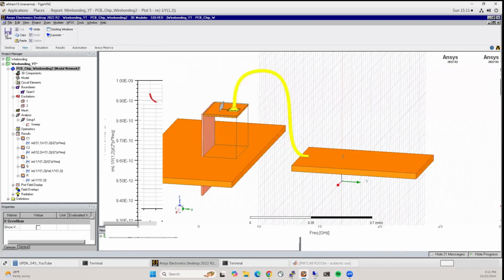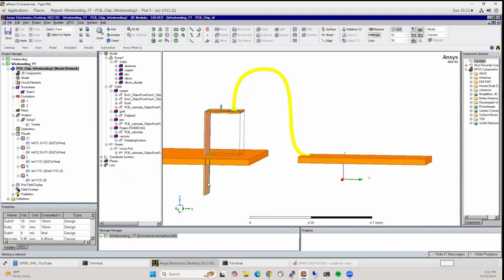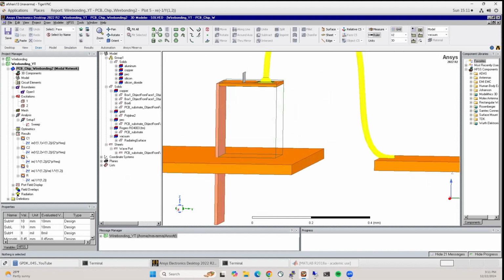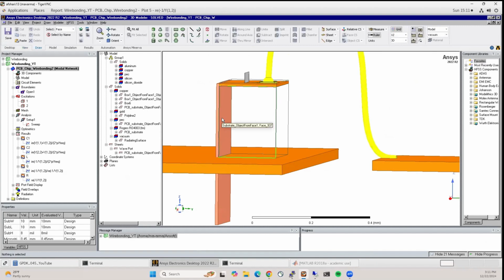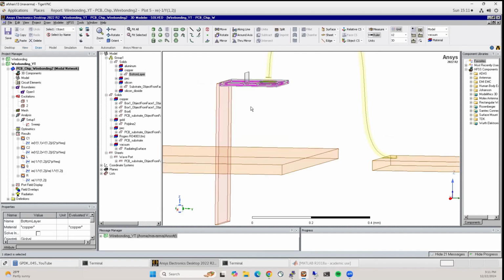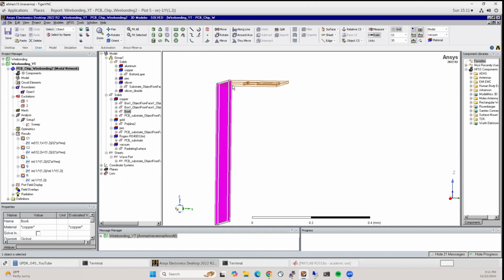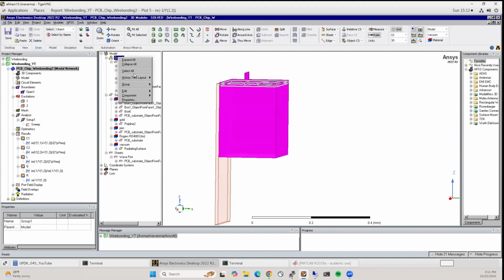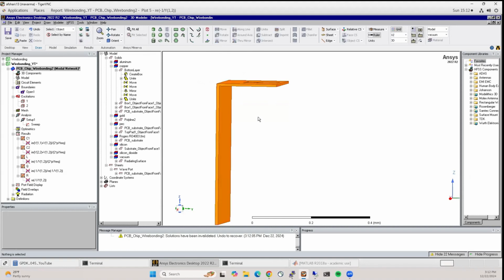So one thing I said is, is this model really accurate? It's not really that accurate, so we'll change it a little bit and see how things change. So what I'll do is I'm going to take this surface. So you see that we have this kind of big sheet of metal, right? We want to make sure the inductance of this metal is not significant. And that's probably the reason why the inductance here is slightly higher than what it should be. So let's change that. So let's select these two sheets of copper. And ungroup this. Unite these.